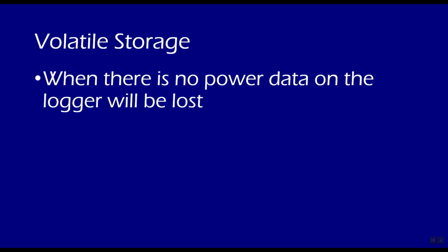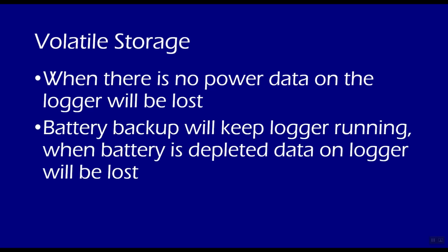An important point to note is that the storage used on the EL005 data logger is volatile. This means when there is no power to the logger, the data on it will be lost. So the battery backup will keep the logger running for a while, but once the battery backup is depleted, your data on the logger will be lost.